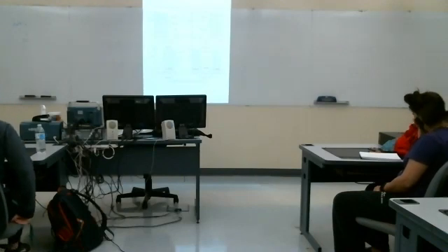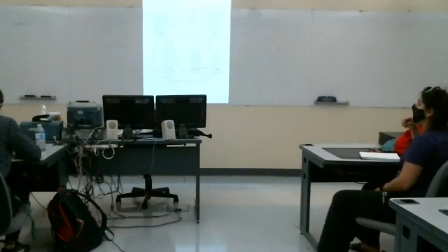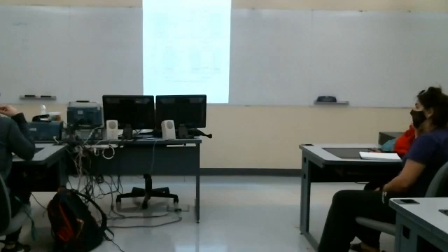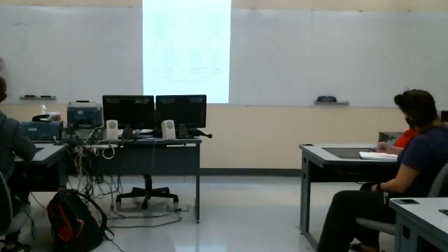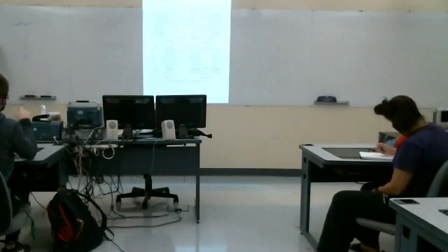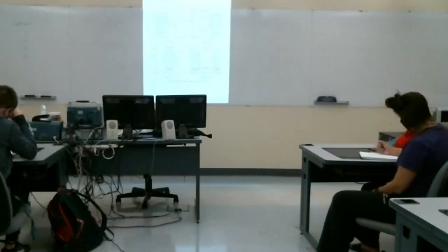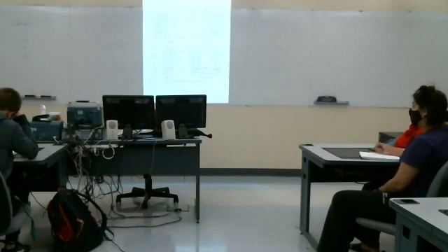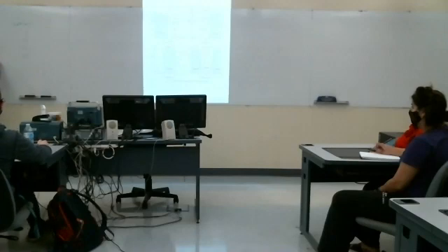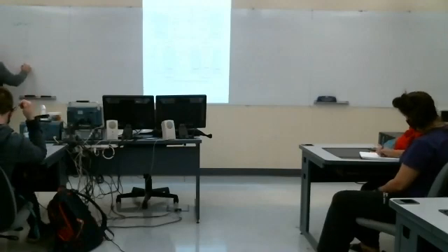Now notice it doesn't matter here whether it's plus or minus 1. The plus or minus actually comes in with regard to the phase angle. This is the absolute value. So plus 1 and minus 1 would have the same dB value. 1,000 would be 60. Notice as our gain goes up by a factor of 10, the corresponding change in dB is just 20 dB. In general, 10 to the capital N power is just 20 times N.